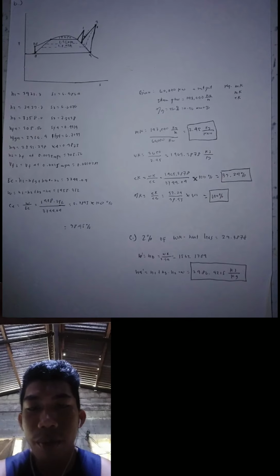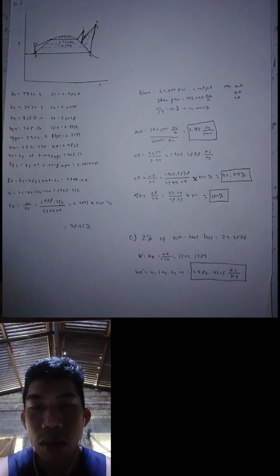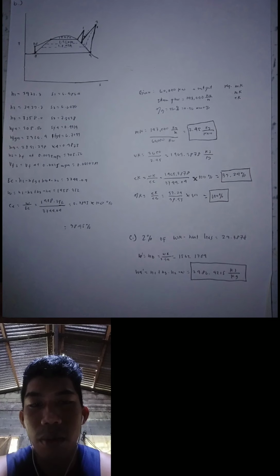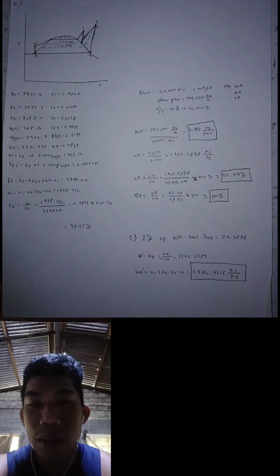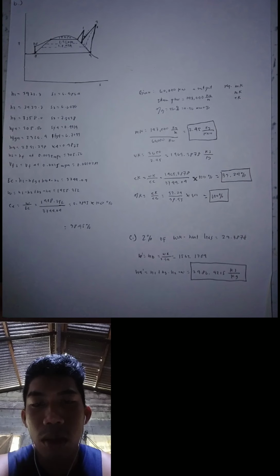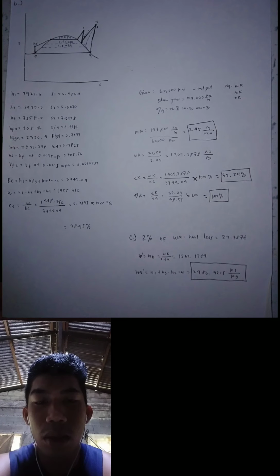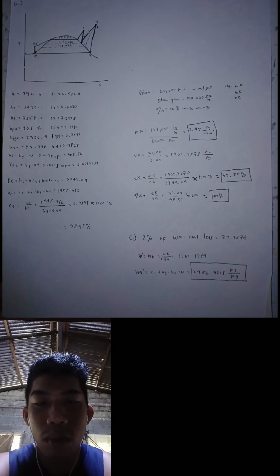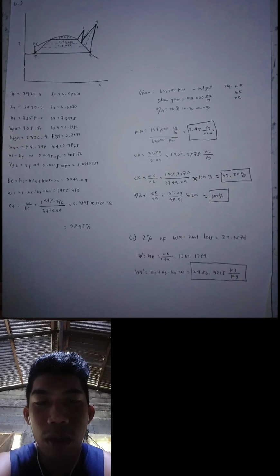So with the given data, we know that it's still the same stage but the pressure has been changed. For this problem, we draw the TS diagram for the actual engine. From the steam table, state 1, H1 is equals to H at 15 MPa at 540 degrees Celsius will give us 3,421.3. State 2, H2 is equals to H at 1.95 MPa and 260 degrees Celsius will give us 2,929.7. State 3, H3 is equals to H at 1.8 MPa and 540 degrees Celsius will give us 3,558.